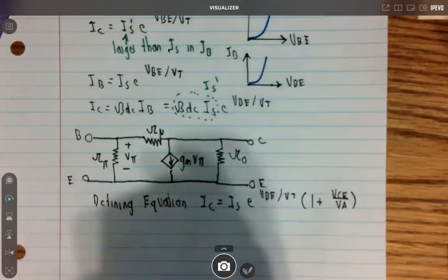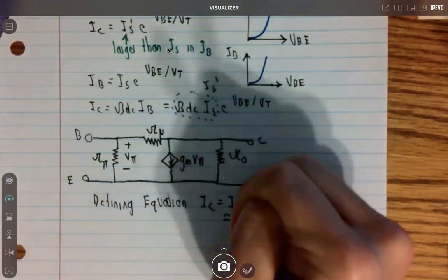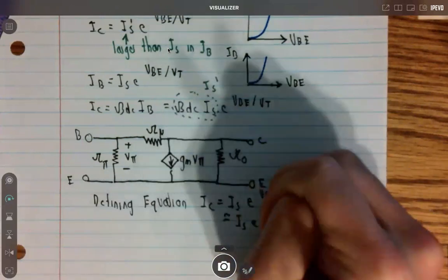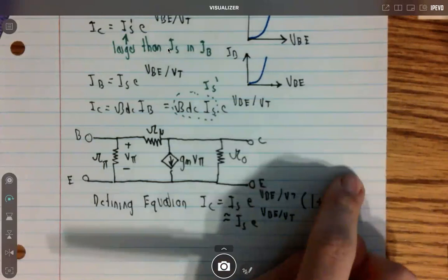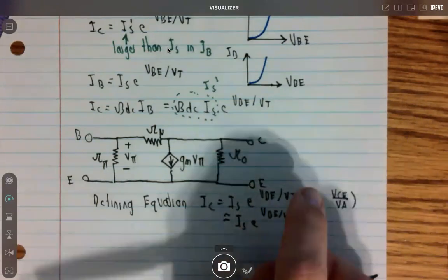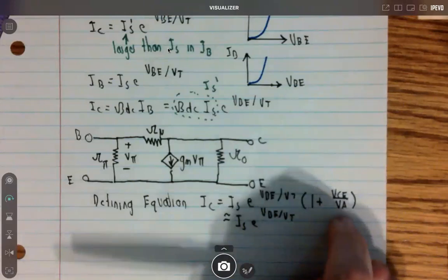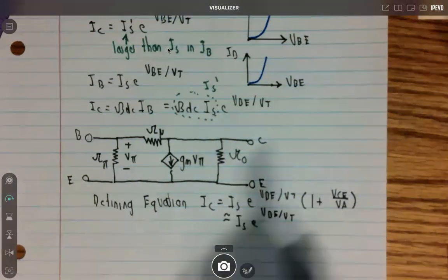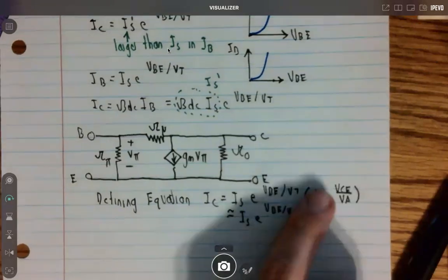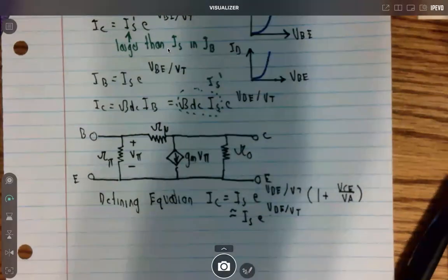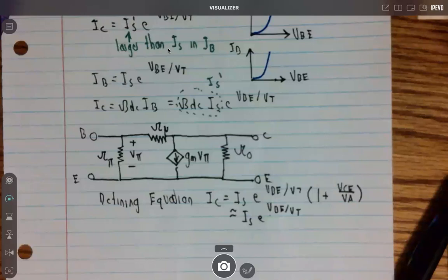And so we approximate this, which we did above in forward bias, as IS e^(VBE/VT), because we forgot about the second term here. We just said that's close enough to 0. If you remember, the VA was around 380 when I did it on mine. So this is a really small number, because over 380 you can almost make this 0. And so it's just 1 times this for forward bias mode operation. And so for the input resistance, let's look at all of these in particular and understand how we get them and how we come to this conclusion.